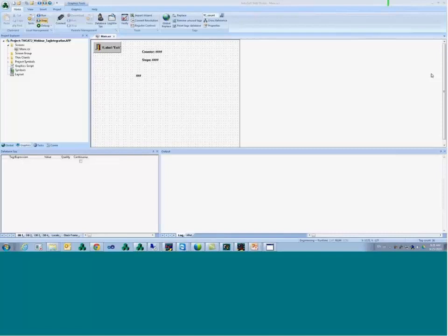So here's the thing. When you have a device that's going to run both the control and the HMI, if you're going to run that on an ARM, you may consider having a small application. And by small application, I mean a small number of screens, a small number of tags, and by small, let's say 500 tags. You shouldn't consider having thousands of tags in that case. Even 2,000 tags on Windows CE with 50 screens on the ARM processor, then you're really pushing it to the extreme.